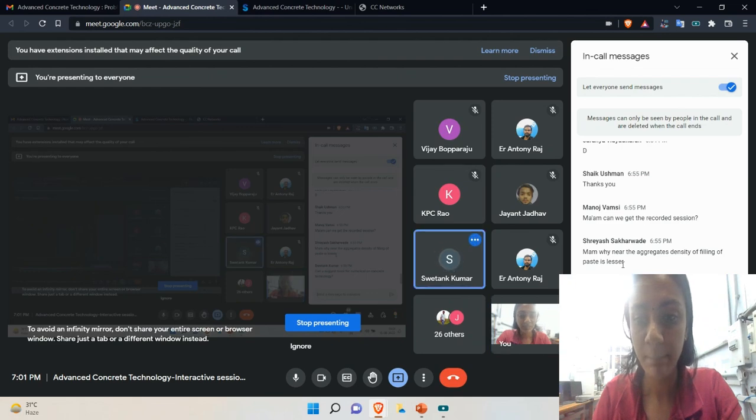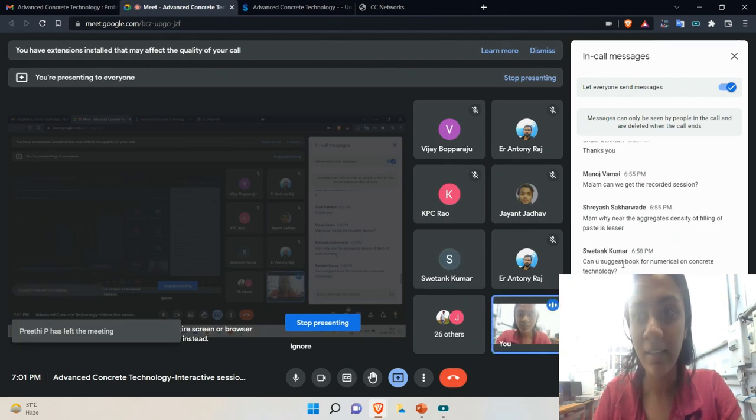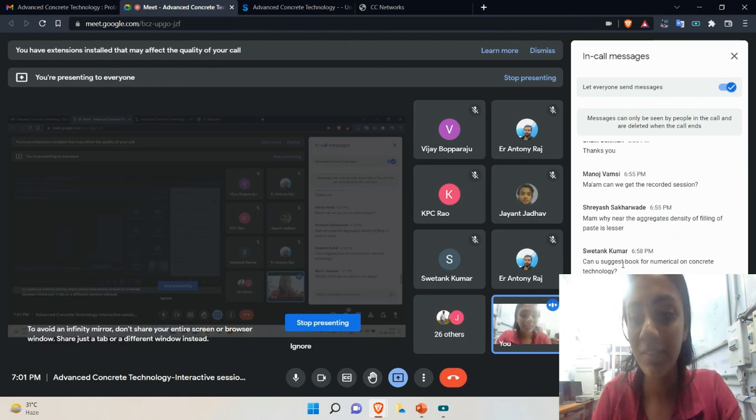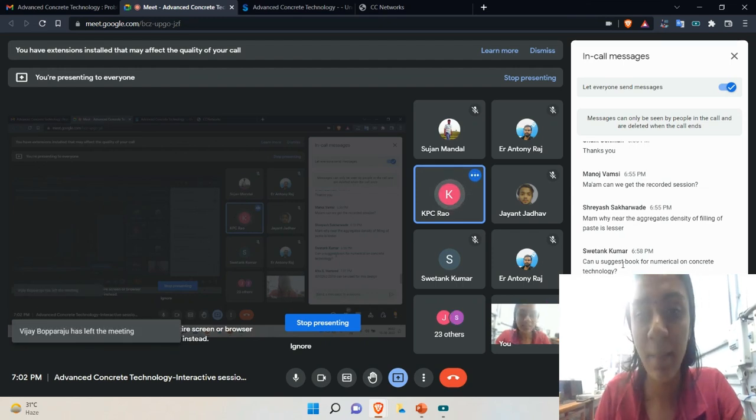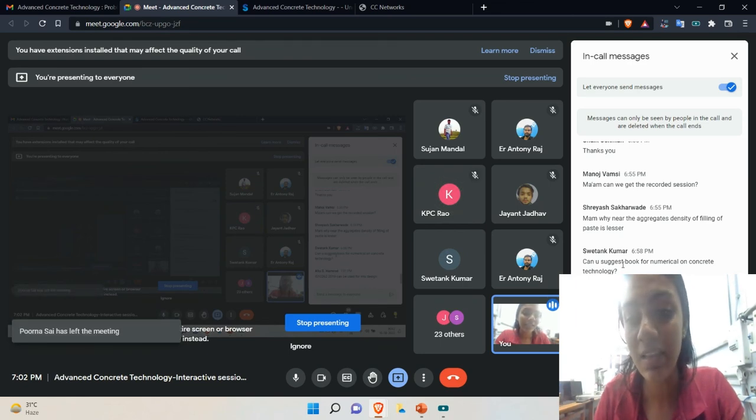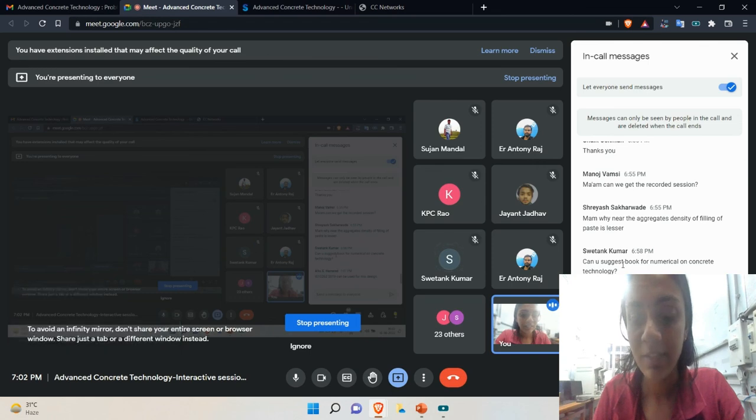Yes, IS 10262, thank you, Afia. I was trying to get the number. IS 10262 can be used for mix design. It gives the various design mixes, depending on how much slag or how much fly ash is used. I mixed it up with IS 456. Based on that, I think there are six or seven numericals given in the appendices. So Shwetank, please make a note of that IS number. You can get them from that.